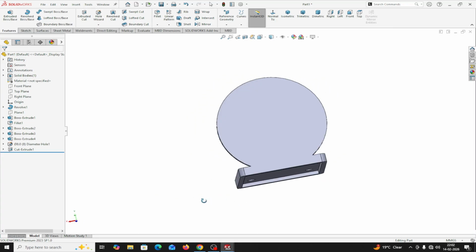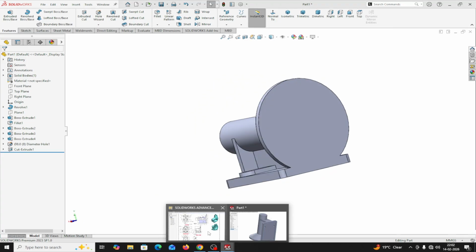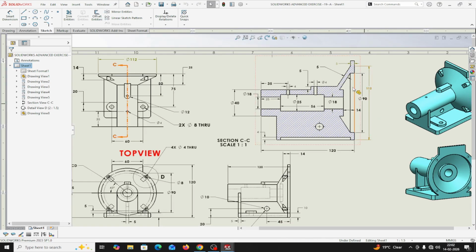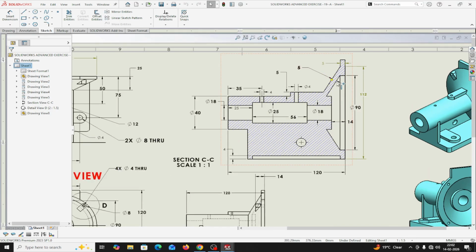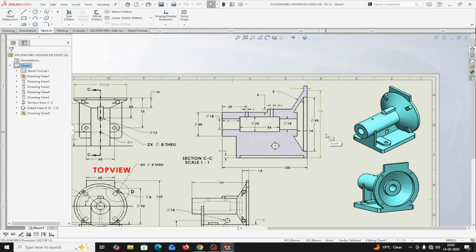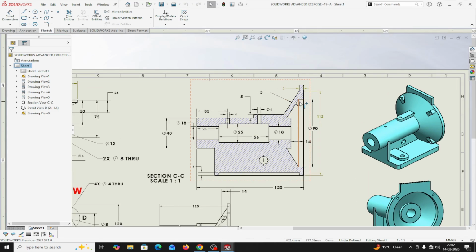Now if you see the section view, now I will make this portion. You will see here is a cut. This is the 5 mm wall. This is an inside cut. The diameter of that cut is 90 mm, and this is the 5 mm wall here. And approximately 5 point something is this straight portion.